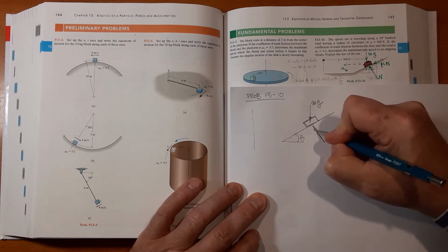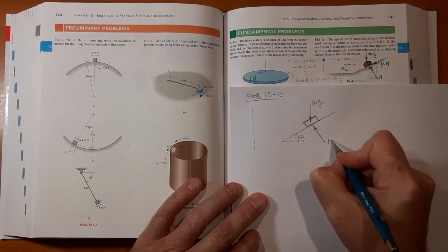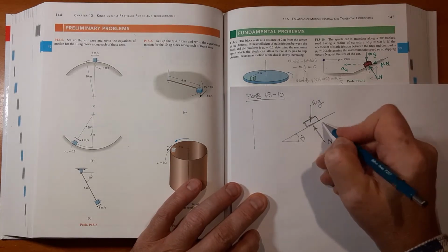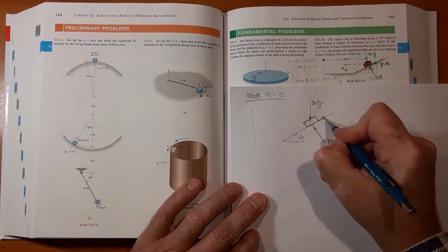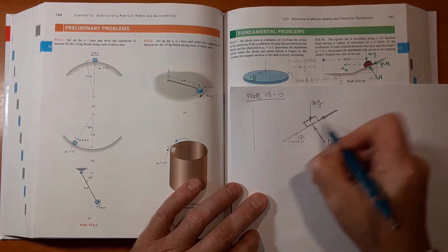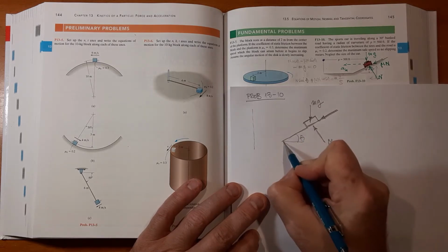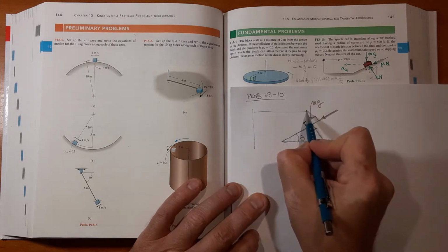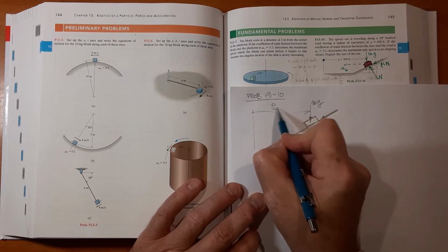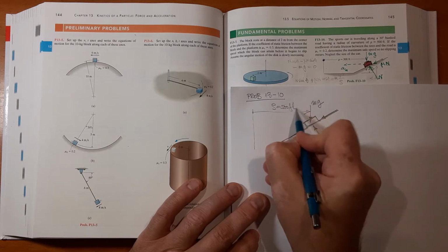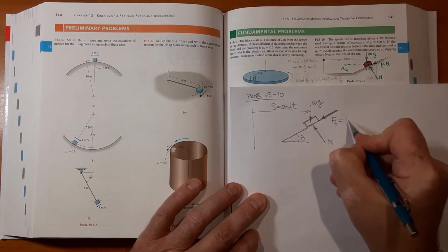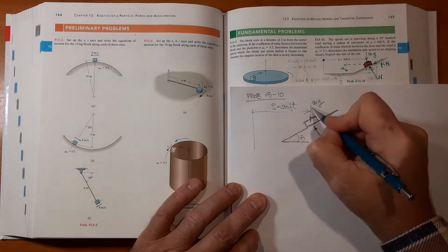Then I have the normal force reaction from the surface, and then we have the friction force, and this is the limit case. So the friction force opposes the car slipping outside, towards increasing the radius of curvature, 500 feet. This friction force is the static coefficient of friction times the normal force. Okay.